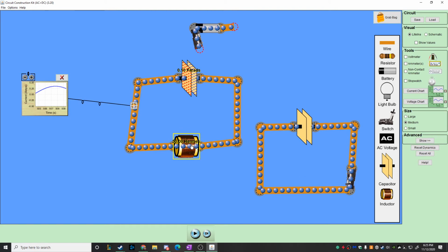So can you all tell me what would the value be, is this going to be easy to calculate? Not exactly, but it'll be close enough. What would the value of the omega be for this system here? Where you do 1 over square root LC. 1 over the square root of 5, yeah, exactly.